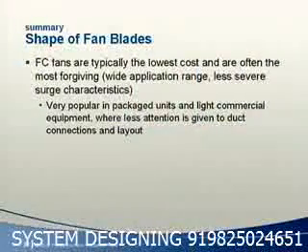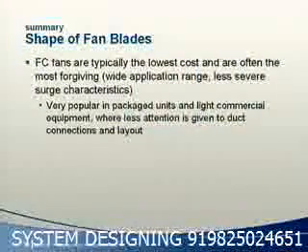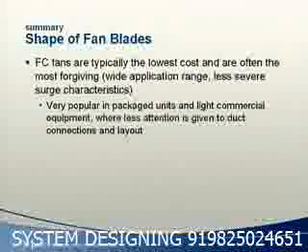To summarize this section, forward curve fans are typically the lowest cost centrifugal fans. Because they have a wide application range and exhibit less severe surge characteristics, they are also often the most forgiving choice. This makes them very popular in packaged units and light commercial equipment where there is a tendency for less attention to be given to duct connections and layout.